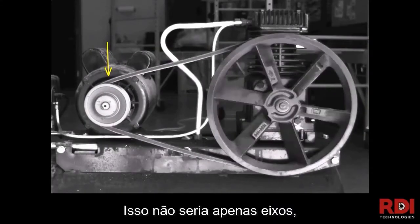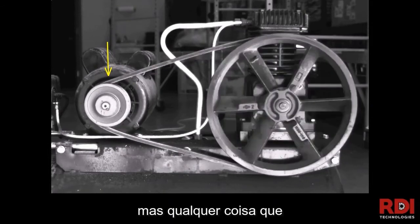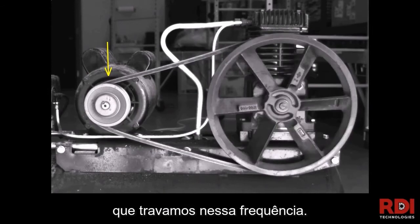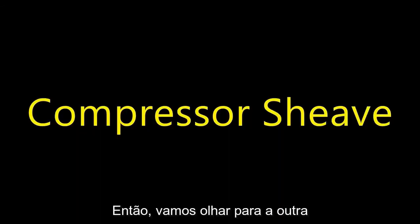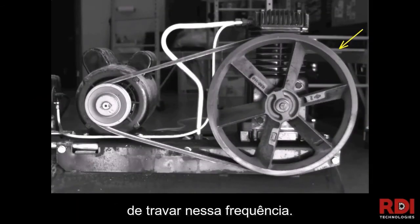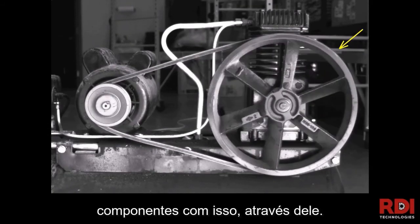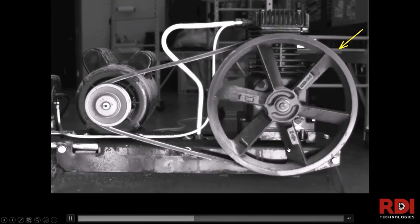So this would be, sort of not just shafts, but anything that's rotating. So this would be the sheave here that we've locked into that frequency. And then we're going to look at the other sheave here to be able to lock into that frequency. So again, you can inspect multiple components with this throughout it.